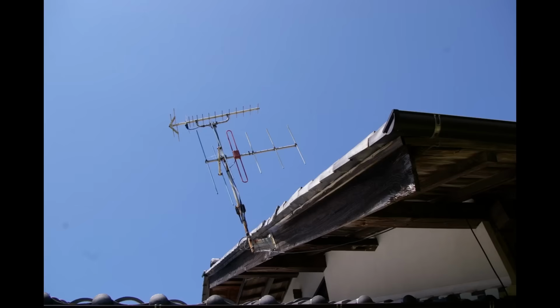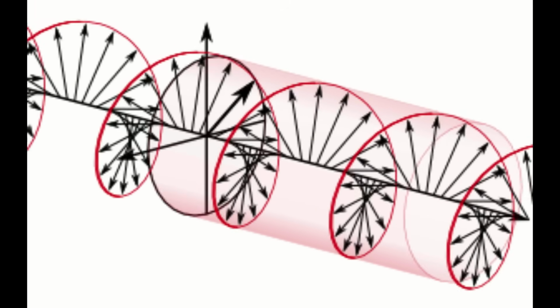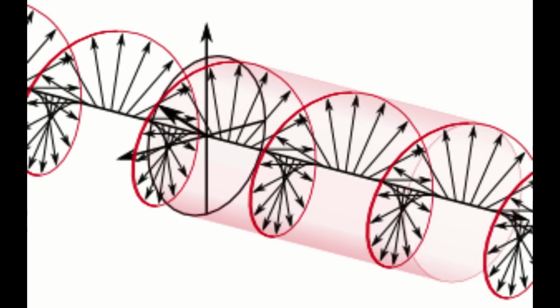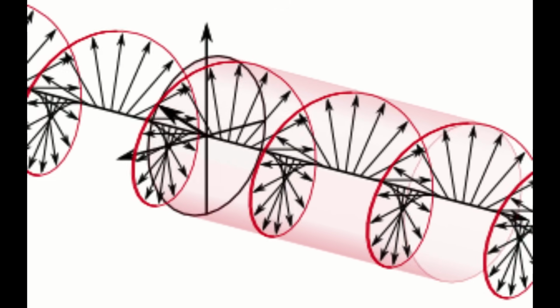When you got satellites hurling across the sky, this isn't as convenient. Most satellites that aren't geostationary tend to spin a little in relation to an observer on the ground. If the polarization was linear, then you'd constantly have to turn your antenna to compensate. So these kinds of satellites instead use circular polarization, which isn't as sensitive to the transmitter spinning around its antenna axis. These come in two flavors, right-hand and left-hand polarization.